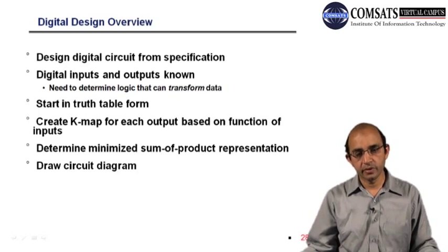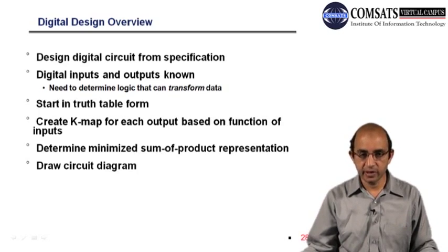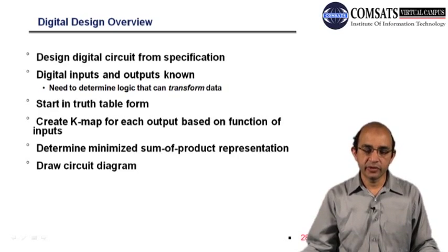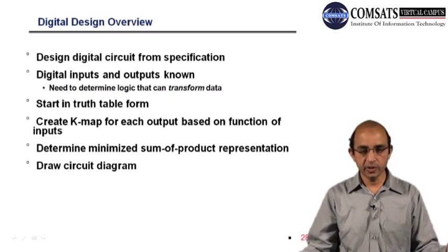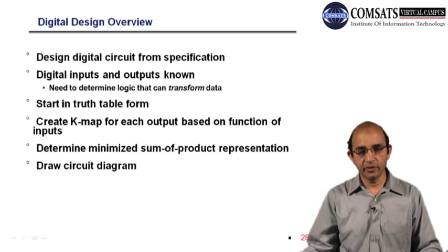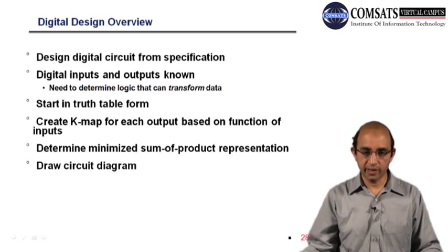After having the truth table, obviously you wish to have simplification, and there are different techniques. You can use the K-map for simplification, or you can use the Boolean axioms. But in K-map you have a predefined number of steps. If you have a Boolean expression or minterms or sum of products, you can straight away map that Boolean function onto the K-map, and then look for quads, squares, pairs, and have the simplification.